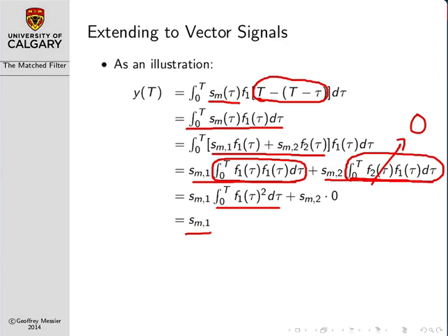And so, to close this section of the class off, when we match to our basis function signals, we can think of the demodulator as an analog signal to signal vector converter that maximizes overall signal to noise ratio. And the example that I did on this particular slide assumed no noise. What happens if we would have had noise in this example?